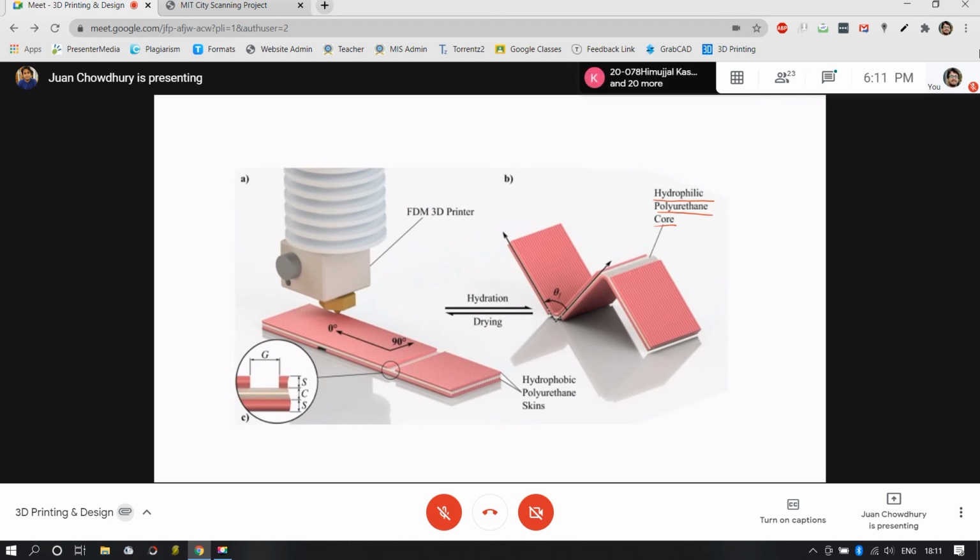All right. A very generic application of shape memory alloys is actually certain pipe attachments. Okay, of course it doesn't happen over here, but in places where the winters and summers are extreme, there is leakage due to expansion of pipe during the summer, and because there is a contraction of metal in winters, these systems are now loaded with shape memory alloys which counteract the otherwise.